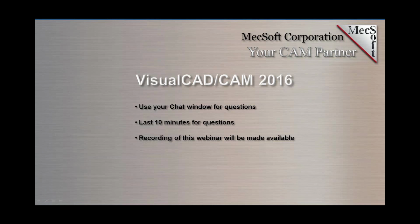Well, there's one that you could perhaps answer, Uday. Using the cabinet feature, will it handle a SOLIDWORKS assembly served as an IGES? That's a great question. Yeah, you could import any solid surface geometry into VisualCAD, and then you should be able to use a cabinet explode decomposition feature to explode them into flat panels. The SketchUp file was just one of the cabinet files I use as an example, but you should be able to import any solid surface geometry to be able to explode it.